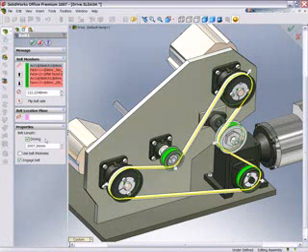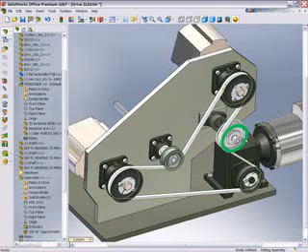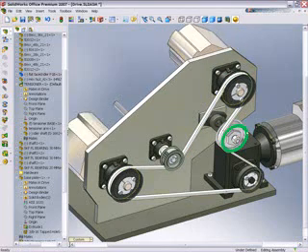By selecting the driving option in the Belt Chain Property Manager, the user can set the length of the belt and the belt tensioners will update to the correct position for that particular length. By using the Engage Belt option, all the pulleys in the system will rotate at their correct ratio as the pulleys are put into motion.